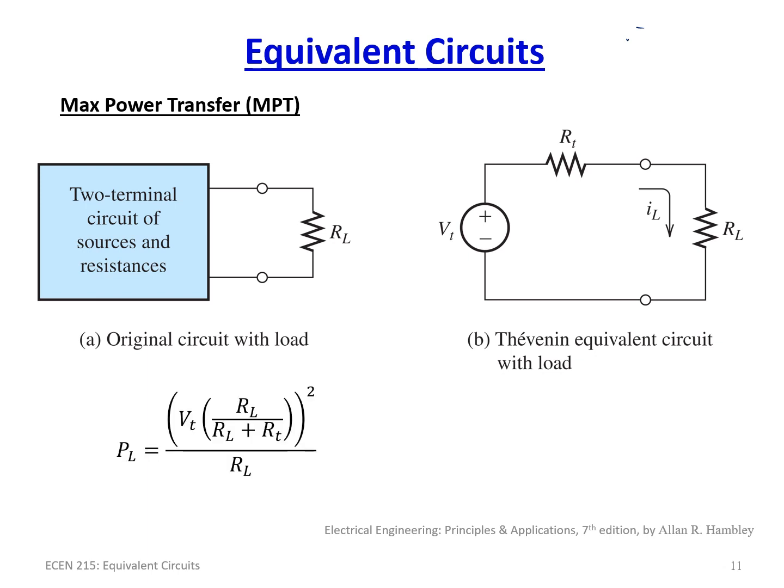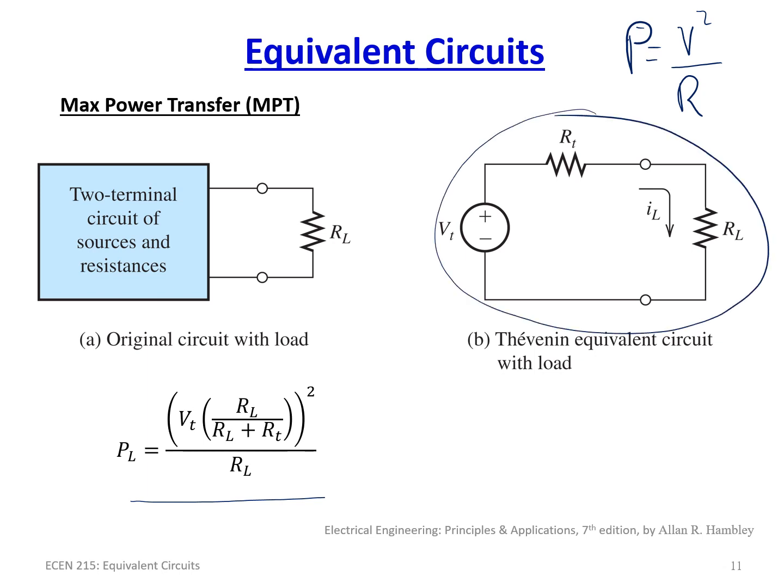Well, first of all, power in the load is determined simply because, remember, this is a voltage divider. And if we remember, our formula for power using voltages is V squared over R. So that's what's governing this equation right here, is V squared over R. So what is the voltage across RL? Well, right now we've created a voltage divider circuit again, where RL is, if you will, R2 of the voltage divider.